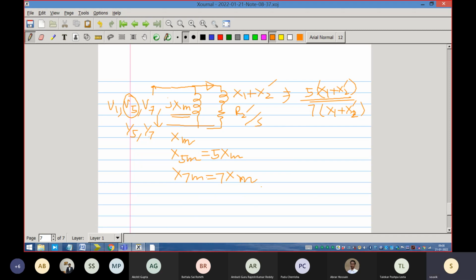So it may be 1/5 and 1/5, not so much less, because R2 dash by S is not changing. So this impedance is decided by R2 dash by S plus j(X1 plus X2 dash). Only the reactive part is proportionally increasing, but still there is some current.